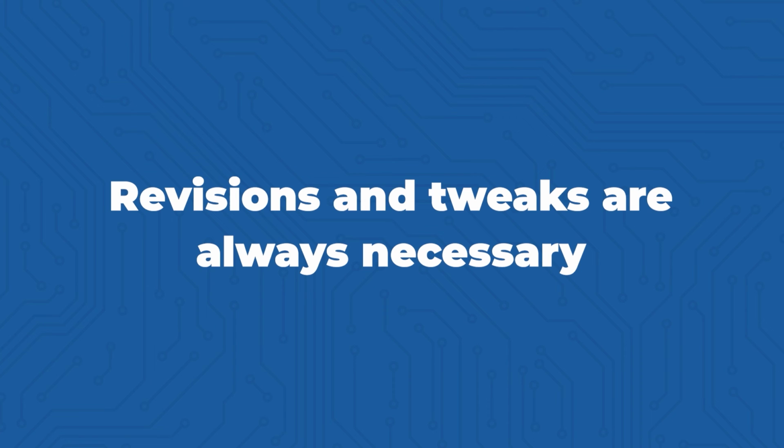What will happen is you order the PCB prototypes, you get them back, you evaluate them, you identify any problems that you found. Then you have to figure out solutions, design changes you want to make to fix those problems that were discovered. You'll go back, revise the schematic design, perhaps revise your BOM, revise your PCB layout with these changes, order new prototypes, and then begin the evaluation process again. And that will repeat over and over until you finally get prototypes that are completely bug-free.